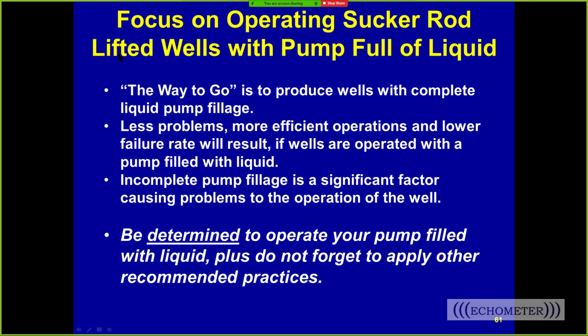So the way to go is to produce your wells with the pump filled with liquid. You have fewer problems, more efficient operations, and lower failure rates when the well is full of liquid. Incomplete pump fillage is a big factor in causing problems when you're operating your wells. Be determined to operate your pumps filled with liquid.